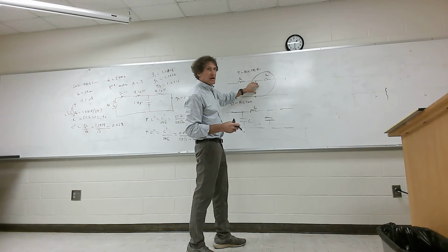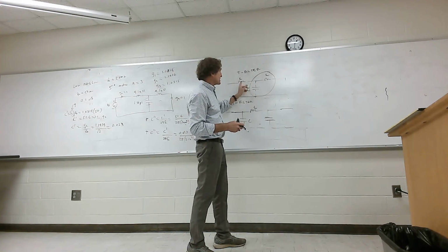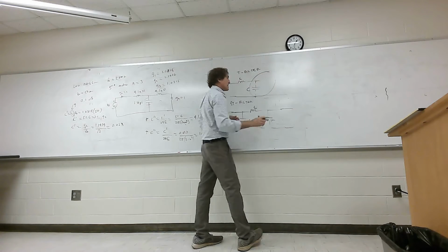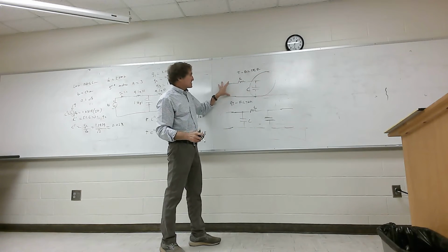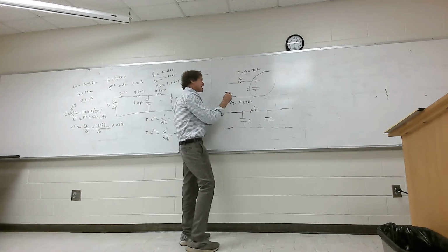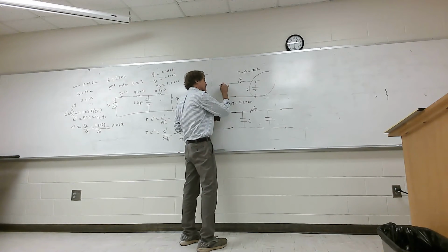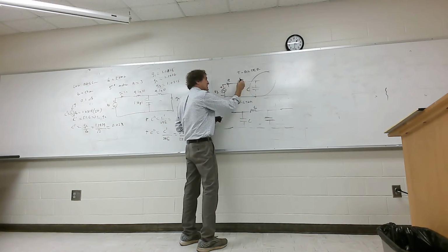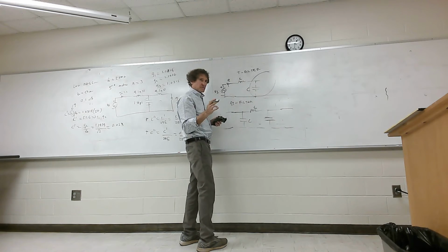And just think about this. Anytime you have a series LC circuit, what if this didn't exist here? Right? What happens at resonance to this thing? Well, at resonance, if I put a resistor R and a source value Vs, these impedances cancel, right?